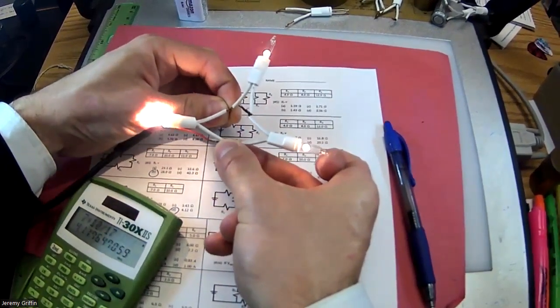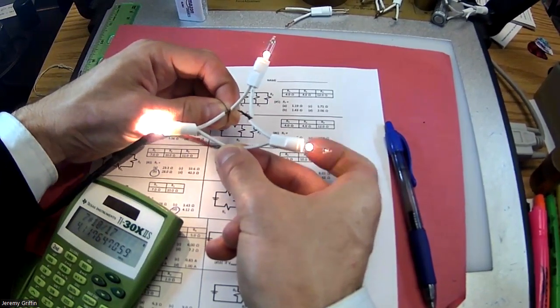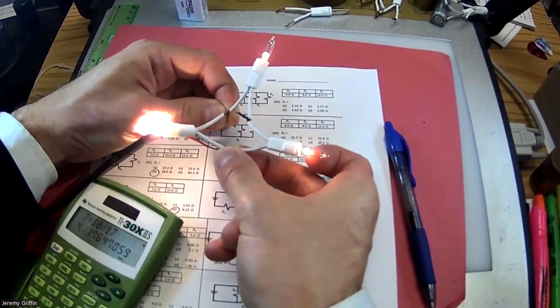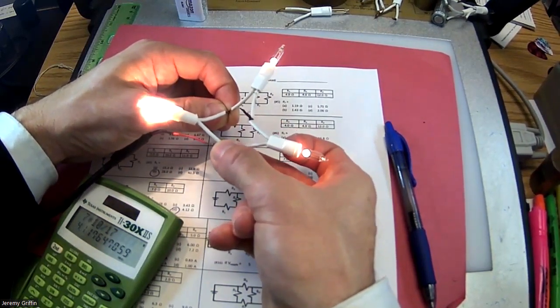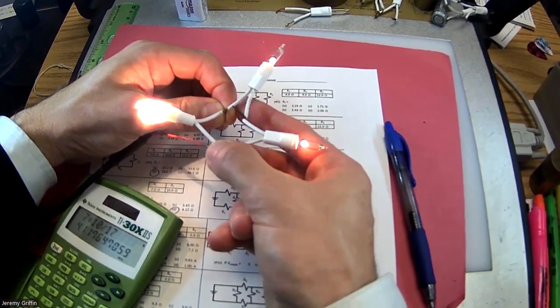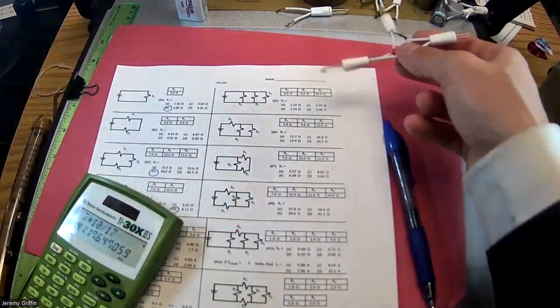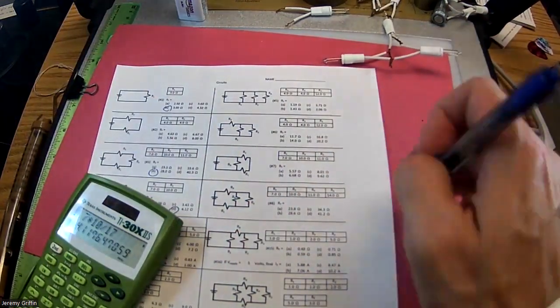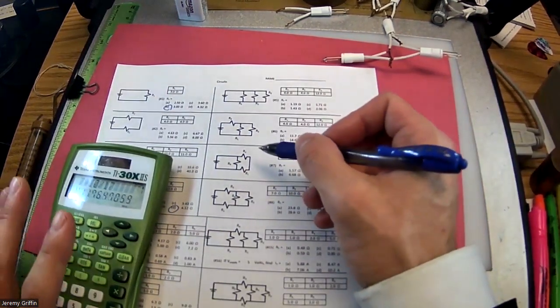You guys see that R3 is really bright and R1, R2 are really dim? Okay. Now, part of that has to do with the fact these are all the same resistance. All these bulbs are. So one way to think of it is the bright one is getting the full 5 volts across it. And the dim ones, well, they're each getting 2.5 volts. This guy gets 2.5 volts. This guy gets the other 2.5 volts, right? And then you step back to Ohm's law and you can figure out the current going through. Okay. So what's the total resistance of number 7? Right now, there's a process with these.